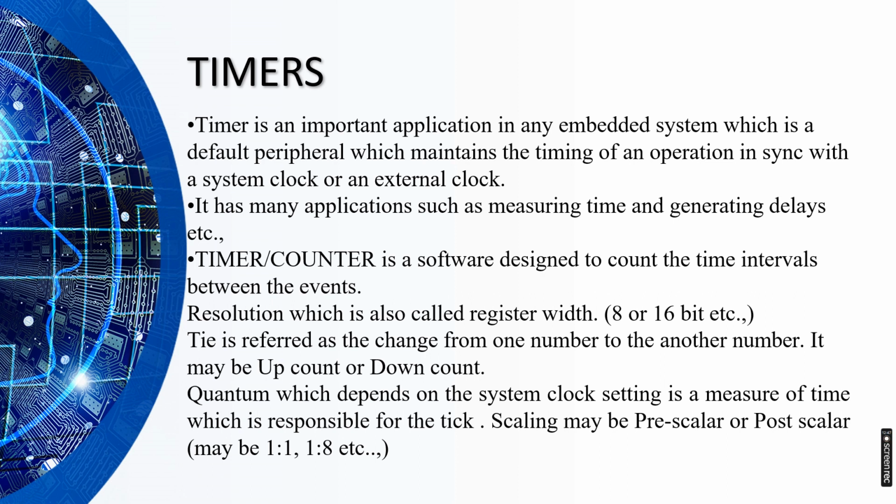Resolution, which is also called register width, can be 8-bit or 16-bit, etc. Tick is referred to as the change from one number to another number. It may be up count or down count. Quantum, which depends on the system clock setting, is a measure of time which is responsible for the tick. Scaling may be prescaler or postscaler. It may be 1:1, 1:8, etc.